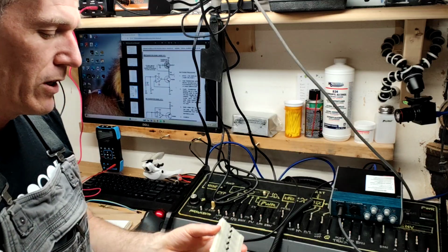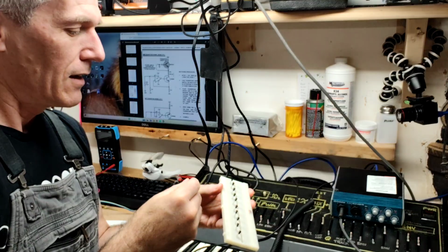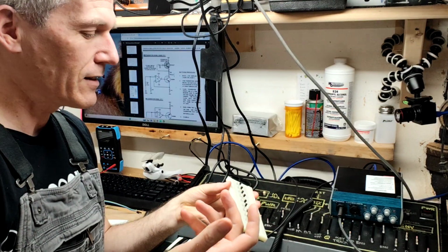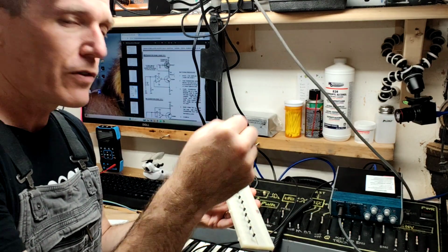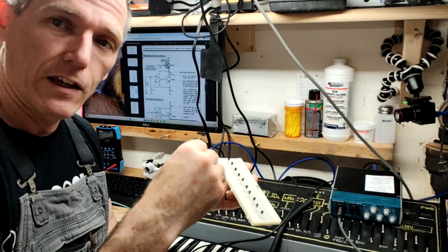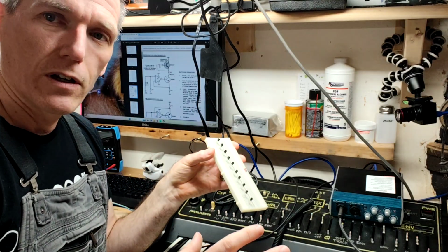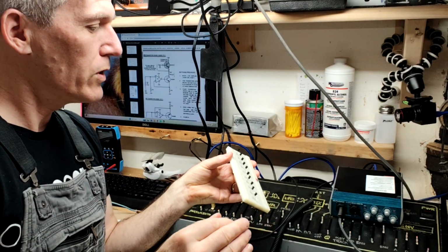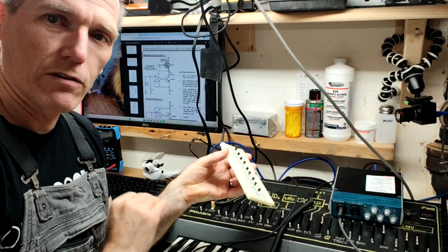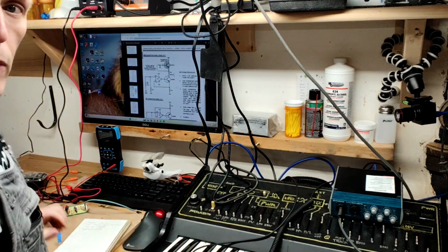Why do we need to match? Well, these transistors, they change properties based on temperature and other things like that. But if you pair two of them together and have them fight against each other in just the right way, if they're matched, a lot of those other terms drop out so that you get a really clean exponential and repeatable behavior. But the first thing you need to do is you need to match them. So how do we do that?